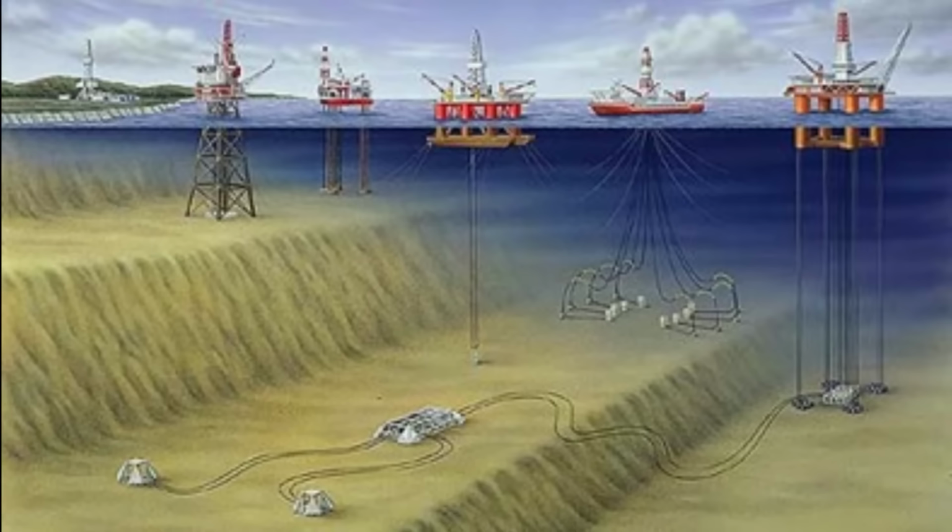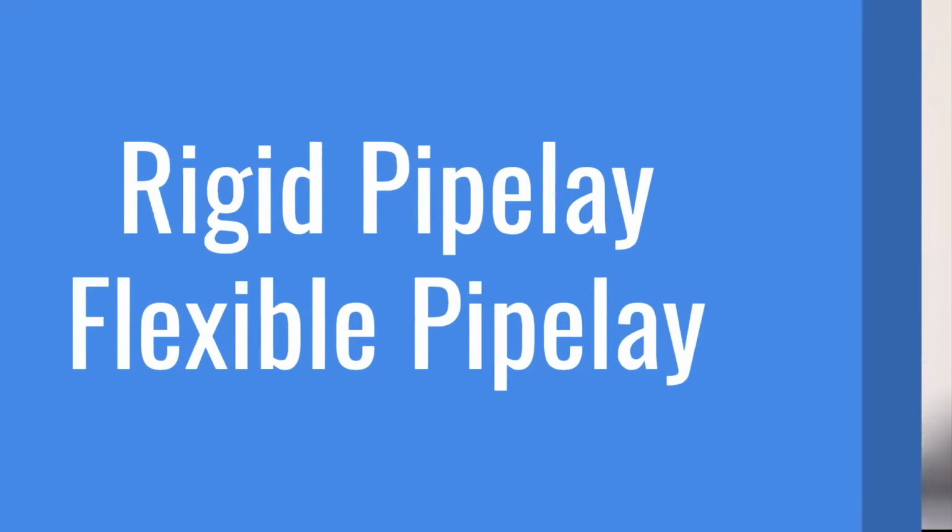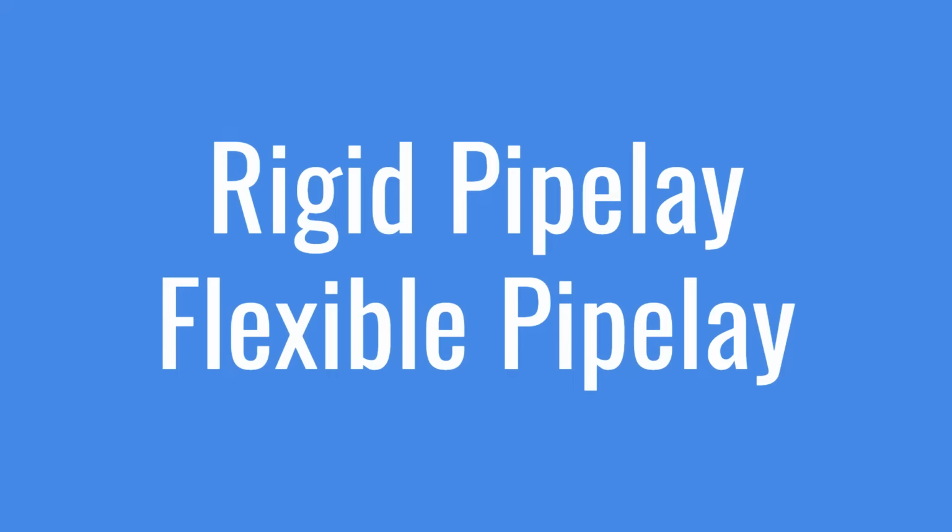These pipes carry crude oil and gas from the drilling platform to the processing platform on the field, and from the processing platform to the nearby shore facility for further processing. These pipelines are the lifelines of offshore oil and gas fields. The majority of these pipelines are 12-meter sections of steel. Some are also flexible. So we normally categorize these pipelines into two broad categories: rigid pipelay and flexible pipelay.